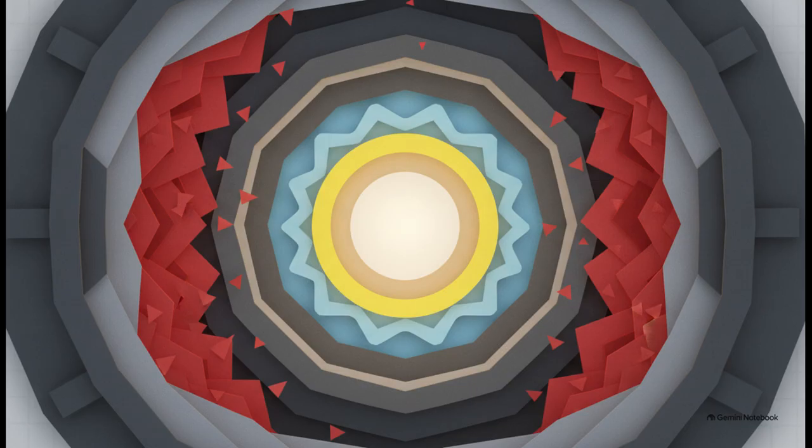The absolute gold standard to prove an algorithm doesn't leak secret keys through microtiming variations is the Industrial Test Vector Leakage Assessment, or TVLA. And the pass threshold for this is incredibly strict. Your t-value has to be less than 4.5 across 20,000 interleaved executions. It is a massive hurdle to clear.